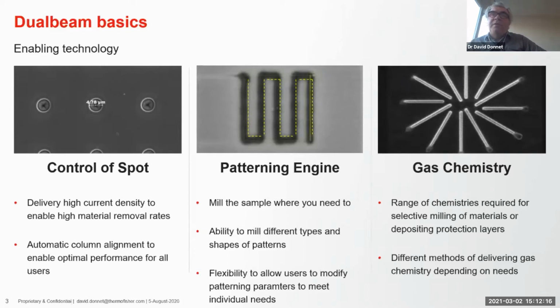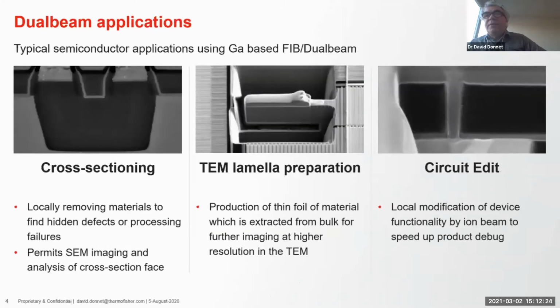So these are maybe the three prerequisites you need to think about for ion columns for failure analysis techniques. Now, the gallium FIB, or the gallium dual beam, is so well established in the semiconductor industry. I think since the early 90s, there have definitely been focused ion beams around. And if we think of the applications, well, actually, if we look to the right first, the last speaker talked about circuit modification or circuit edit. This was actually the original application for focused ion beams.